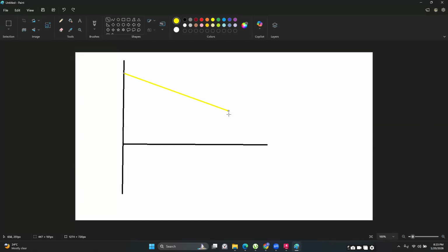It was basically more of a parabola than these straight lines. You're going to see how it looks like in the software. And this axial load and moment interaction diagram, this is how it used to work. Along the y-axis, you have your axial loads, and then along the x-axis, these are your moments.